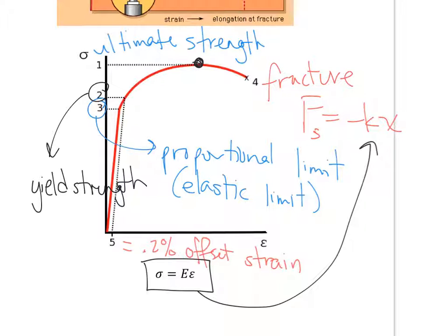I'm going to show you several. I forget if this one shows the actual graph. I'm hoping it does. But look, what did we just talk about, guys? The following properties are calculated from this test. Offset yield, that was the 0.2% offset. That you knew where to draw the parallel line. Ultimate tensile strength, the maximum of the stress-strain curve. Elongation is the strain along the x-axis.